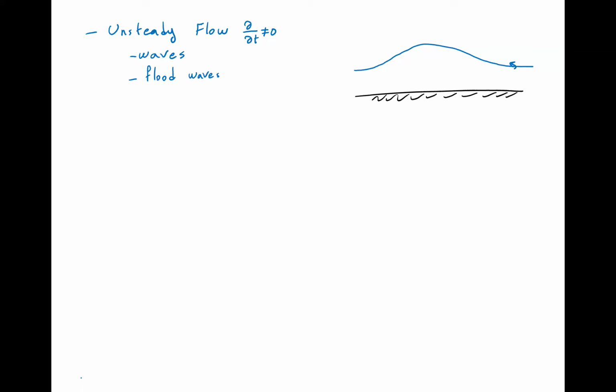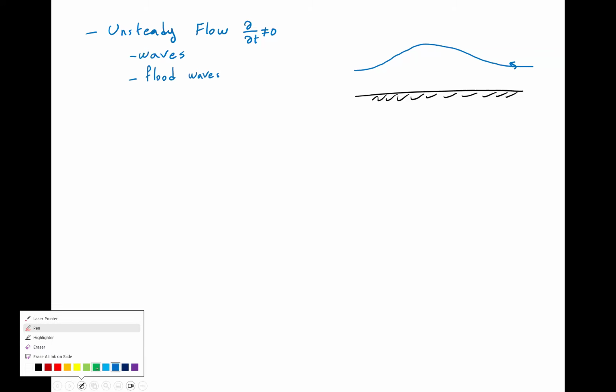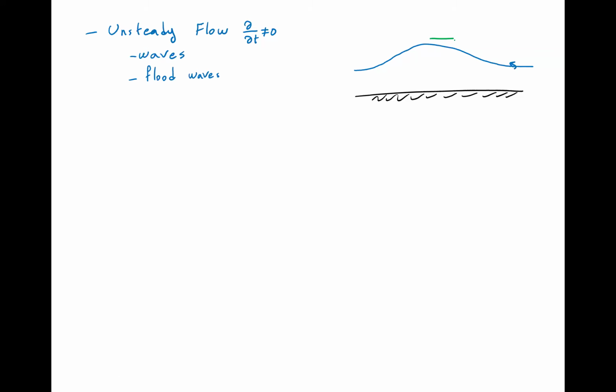Now, what's happening here? First of all, we have this wave, and the wave is traveling at a celerity of c. Remember, we talked about this too. The general flow is from left to right, just to establish some orientation. The wave arrives at some point, this is Hope or something, and depth goes up. The flood arrives, we get a depth of y1, and the discharge goes up because the flood is coming in, so we have a discharge of q1.